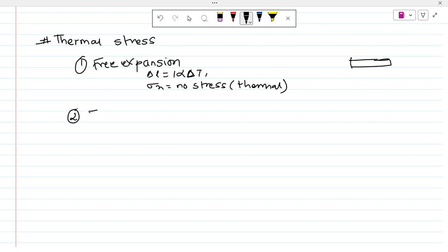But in the fully prevented case, what is the fully prevented case? Okay, so I was talking about this. Sorry, this is free stress if it is fully prevented like this. In this case, we have del L total equals 0.